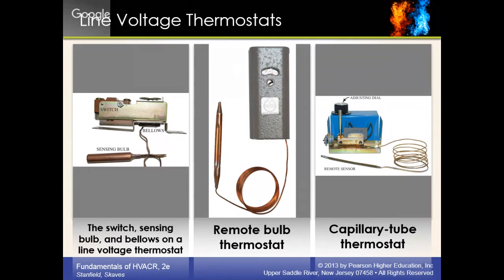The pressure rises, which is going to open. So this will be in line with our compressor motor on the air conditioner. So as the pressure rises, that's going to open and it's going to kill the compressor so we don't overload and burst that circuit with pressure, burst the plumbing circuit with pressure. Okay.